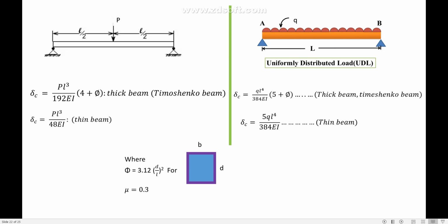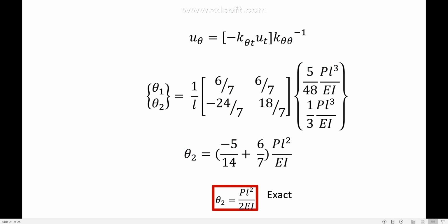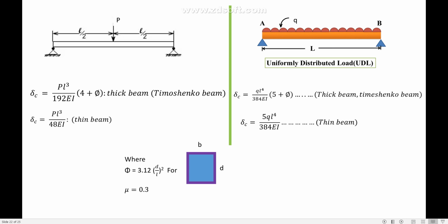I am doing this because I have a mass matrix related to theta rotation as 0. So if I calculate the eigenvalue and eigenmode, I should have a matrix where diagonals are not zero. That is the reason why I am doing this. Okay. Next.